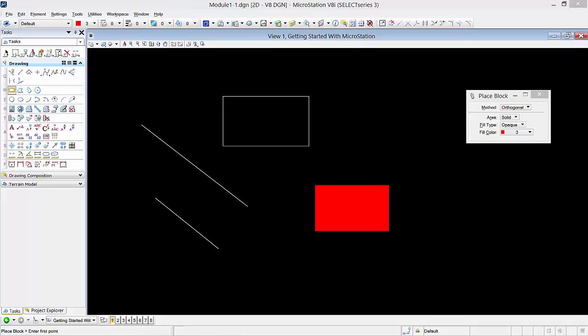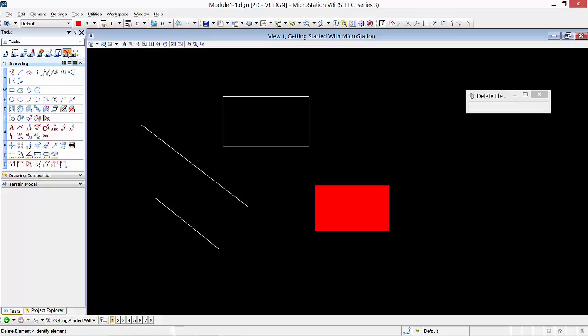command. Let's go over to the Task dialog on the left. You will see a red X towards the right of the main toolbox. This is the Delete Element tool. It's pretty basic. Select the Delete Element tool. Identify element you want to delete. In this case, select one of the blocks you drew earlier, and element disappears. This concludes working with tools. See you in the next video.